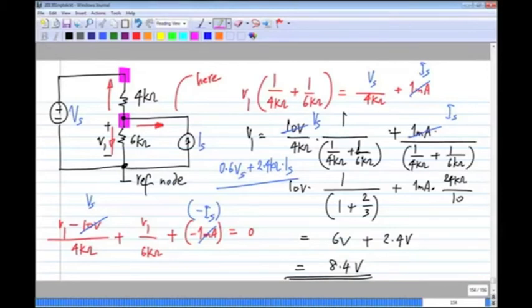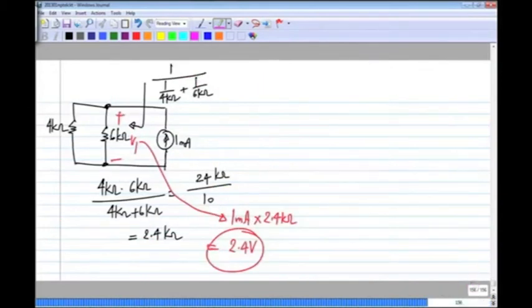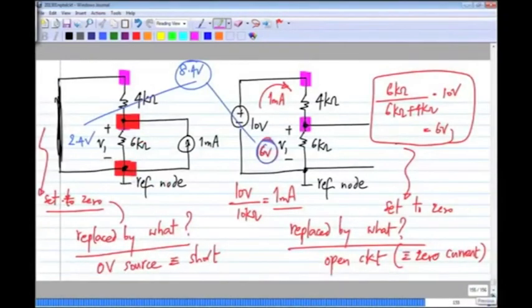Okay. So we solved the circuit with all the sources in one shot, and then we did it with one source by one source, setting all the other sources to 0, and we got the same answer as we should have got, as we expected from a linear circuit. And we also showed here that any voltage or current will appear as a linear combination of all the independent sources. Okay. So that's what superposition is. So that's how we solve for it. Okay.